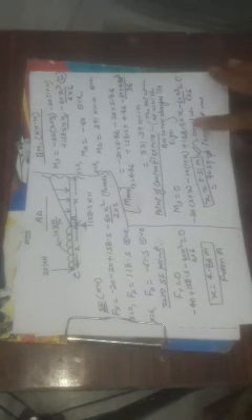Why? The length of portion AD is 6 meter. So this one will be correct. This is our suitable value, the correct value, x equal to 0.51 meter. This will be the point of contraflexure for portion AD, right? Now move to the next portion.